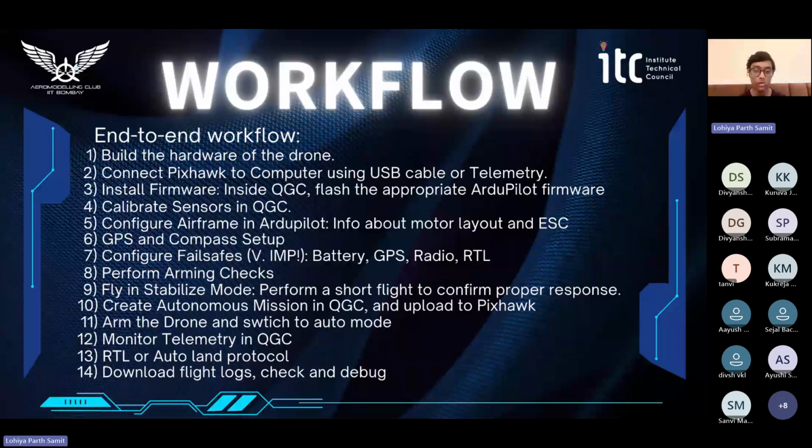And then for the first takeoff, we tend to fly it in stabilized mode. That is, we perform a short flight to confirm the proper response for our given inputs. And then we create an autonomous mission in QGC and upload it to the Pixhawk computer. We then arm the drone and switch it to auto mode to allow it to fly autonomously. We then monitor the telemetry from our ground station in QGC.